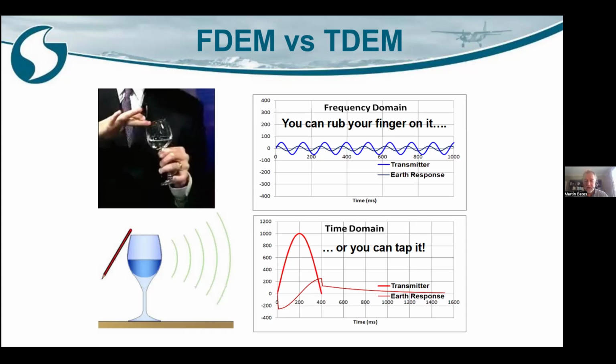You have one coil, which is generating an electromagnetic field. You're running a current around that coil, and it creates a magnetic field through the core of the coil that changes because you're changing its amplitude all the time, up and down. So that changing magnetic field is sweeping through the earth beneath you, and that's a conductive material.